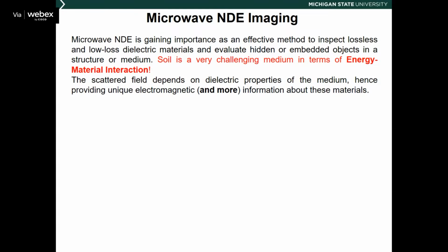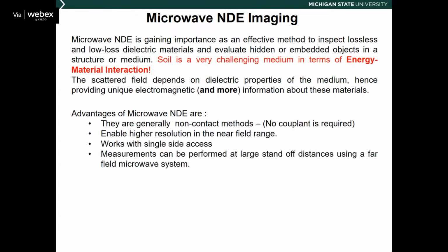So understanding the microwave energy and its interaction with soil is important for us to do good root imaging using microwave. We also know the scattered field depends on the dielectric properties of the medium, so it provides unique electromagnetic information and hopefully gives you more information about these materials.